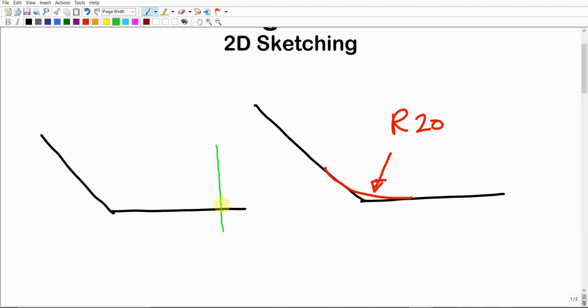that is normal or perpendicular. You have to be pretty sure that this angle is exactly 90 degrees. Normal to the first line, and over this line, you measure a 20 millimeter distance and mark a point. Then from this point, you use the set square to draw a horizontal line that is completely parallel to the first line. Make sure that the normal distance between them equals the radius. Typically, if the radius is 20, it should be 20; if 30, it should be 30, and so on. This is the first step.